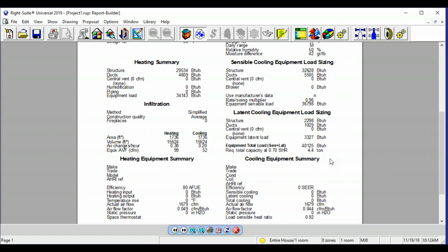If you're not sizing by your sensible, running at a 0.7, so say your area you need to size per sensible, then you need to go over and find out what your running SHR for that unit is. Which I don't recommend doing. I would recommend doing a manual S. Manual S is far more accurate as being able to depict the true unit size that's going to be needed for this, because you're matching the unit with the heat load of the house. And you're taking in a lot more variables, a lot more different temperature sets and settings and stuff like that.